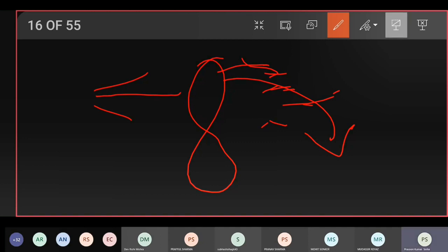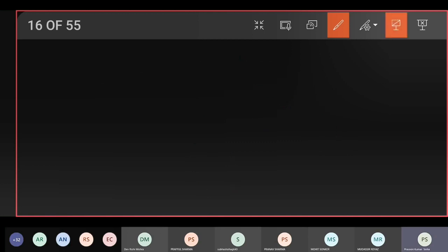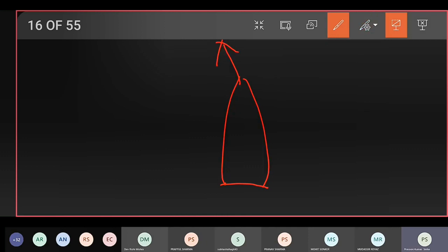When we apply the permanent helm, again going back to the screen, the ship going forward for right-handed screw has the tendency to go to port side. So what we do in permanent helm, we apply little bit of rudder to the starboard. So this movement is neutralized by this movement, and so the ship will go forward in a straight line.